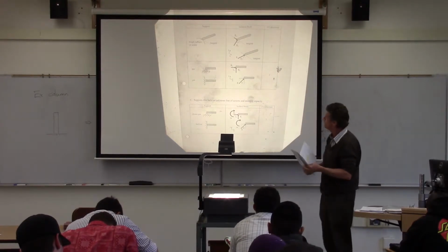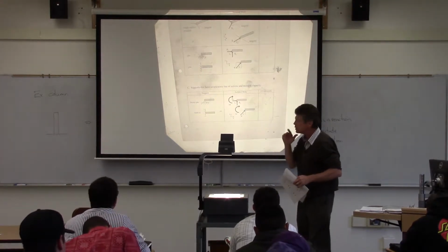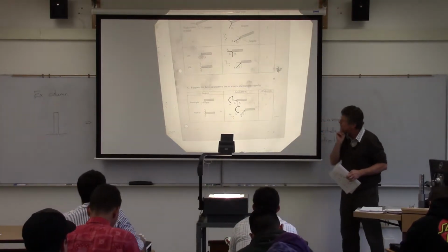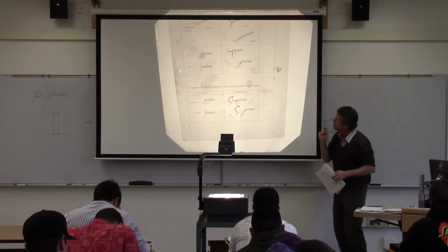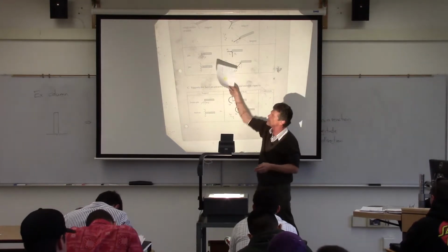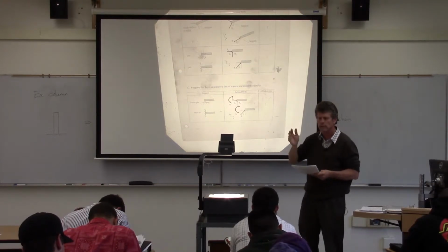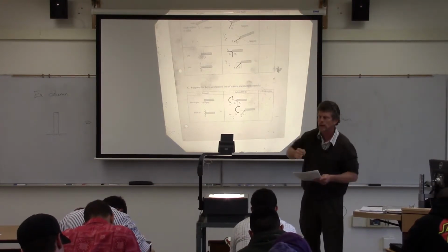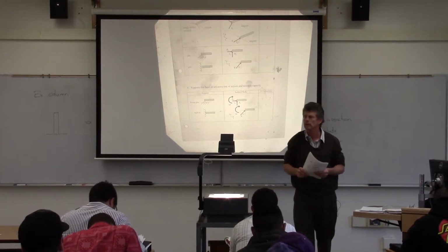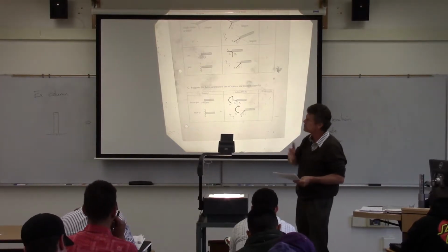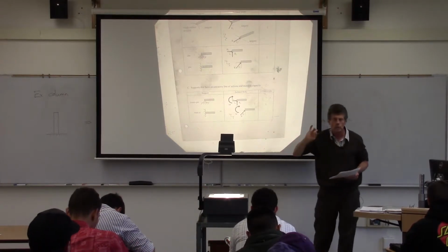Okay, and the last one we'll look at basically is the built-in or frozen pin. Occasionally you'll see that in certain problems. Note, when we go back to the pin here, again, we're substituting forces in the x and the y direction there. But again, think about that pin. If there's a pin there, if I try to rotate that body, nothing really stops me from rotating, right? It's free to rotate. And all the ones we've talked about previously, there's no restriction on rotation at all. This is the only one that's going to have a restriction on rotation.